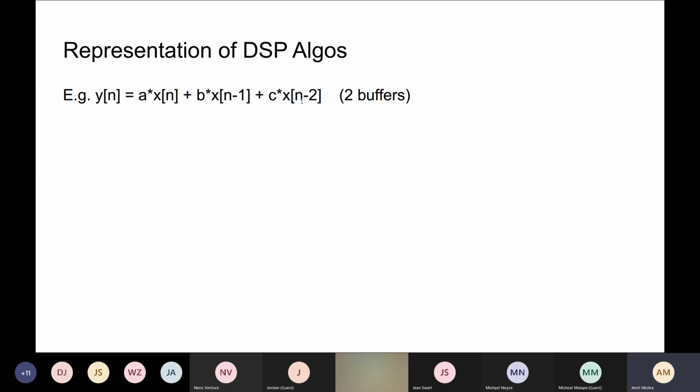It's so common that there is hardware optimized to implement just this chunk of work, multiply and add, which is also called multiply and accumulate, or MAC. The optimized DSP architectures try to implement a single MAC within one clock cycle. So they're hardware optimized to work on lots of MAC operations. That's one way to represent the DSP algorithm, writing an equation.